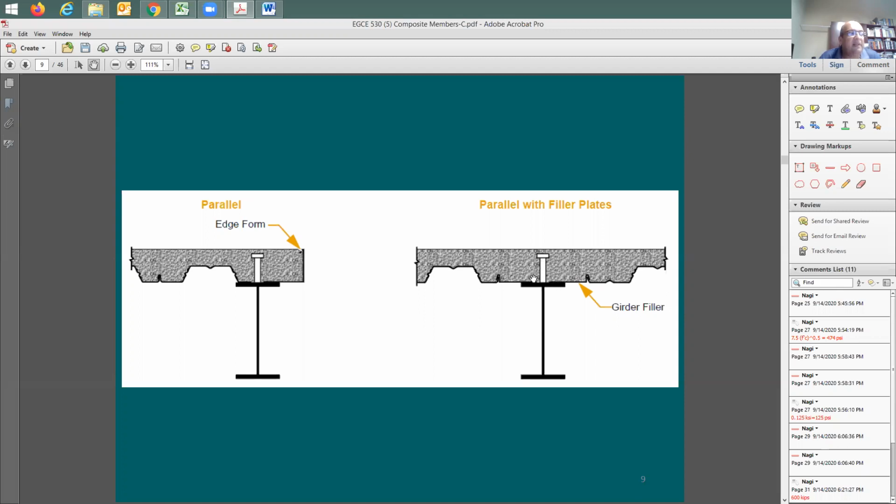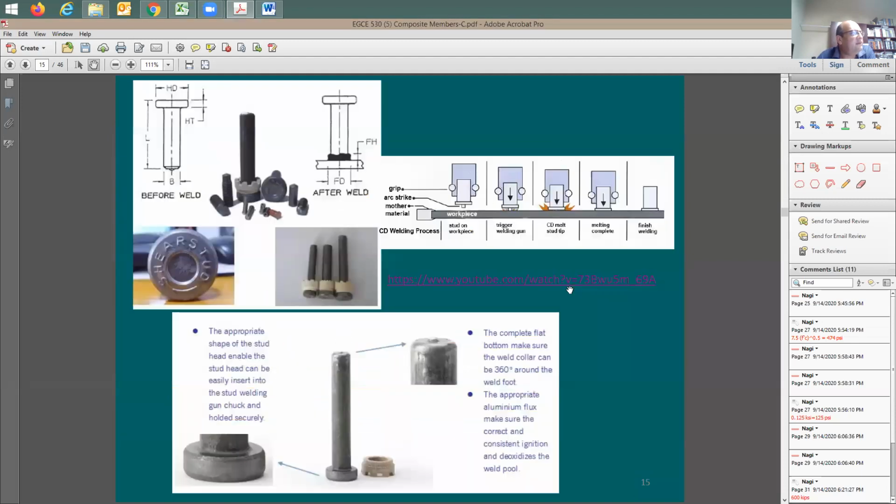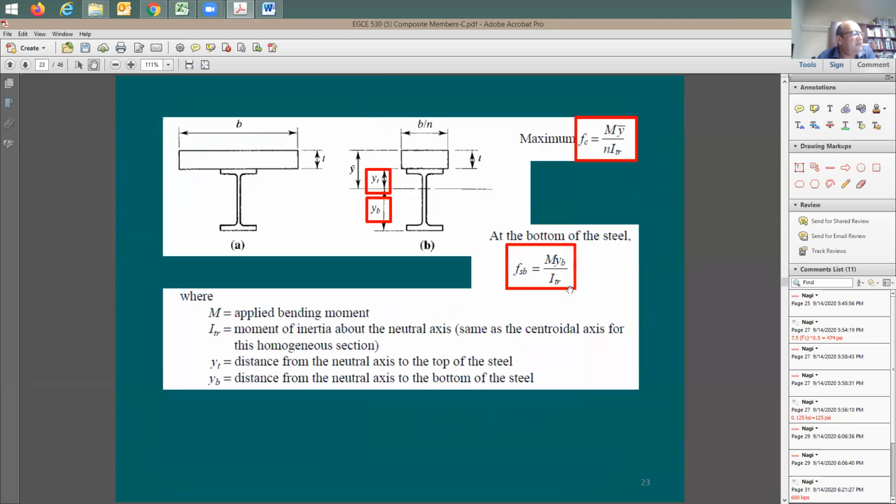If I put plenty of these studs, maximum compression or tension is going to be controlled by the amount of Nelson studs or mechanical connectors that you put in there. If you have enough connectors to transfer compression or tension force from one side to the other side, it means that you have full composite action. So let me move here to my section in the analysis.